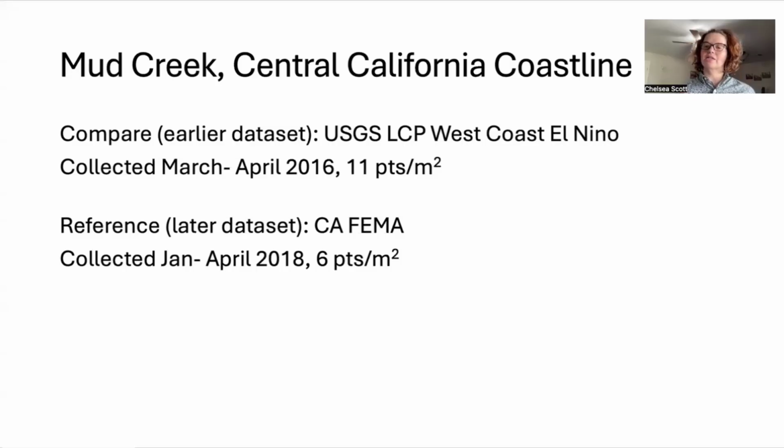The second data set, called reference in the differencing literature, is a California FEMA data set. And this was collected in January through April 2018 with 6 points per square meter. So there's roughly 2 years separation between these data sets. And it's an interesting case where the reference data set actually has a lower point density than the compare data set.